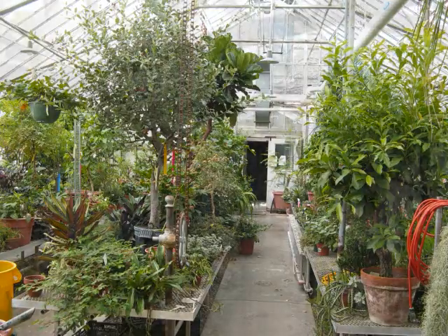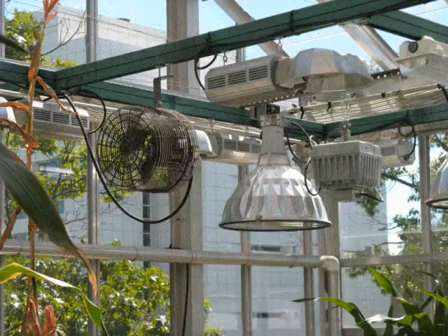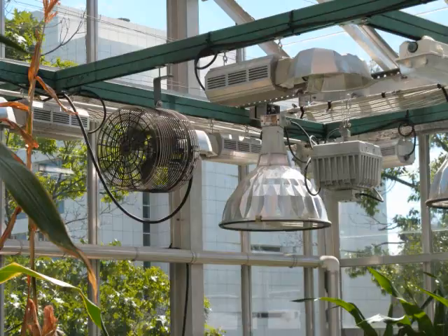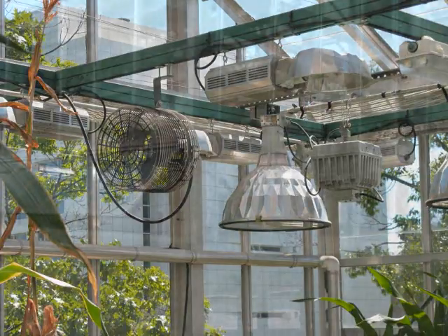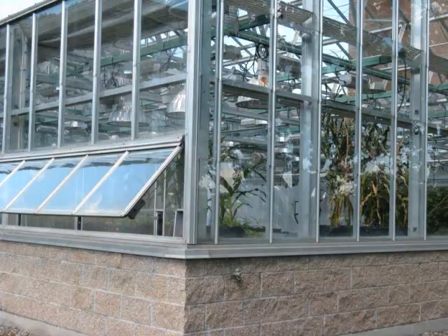Furthermore, it is not reasonable to assume that everything in the greenhouse is necessarily the same temperature. Hot air rises, which means that without constant artificial circulation and proper interior geometry, it will quickly develop a vertical heat gradient, which means that any heat equations that depend on the air all being the same temperature, particularly those with regards to window placement, will produce inaccurate results. The floor can also develop hot or cold spots, particularly as increased plant cover causes shading.